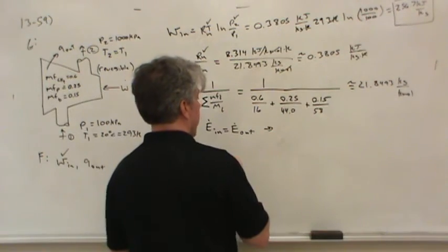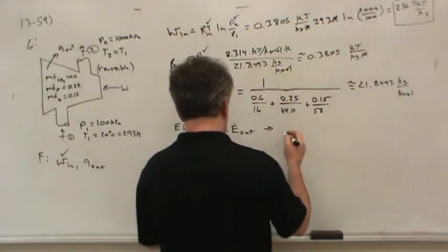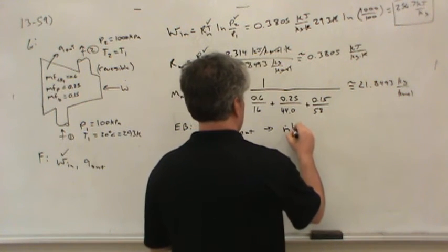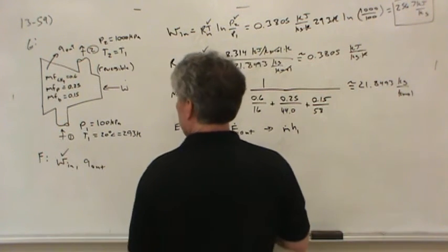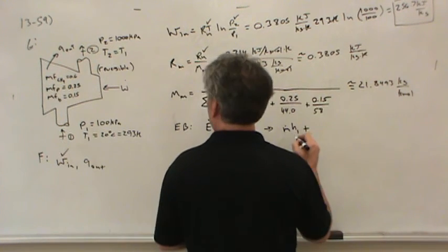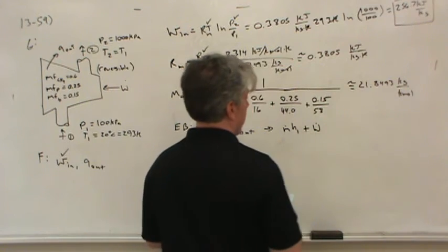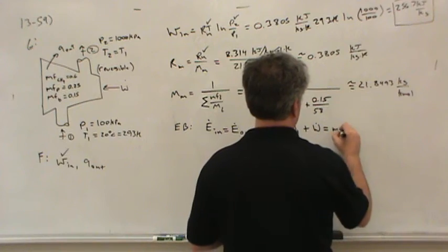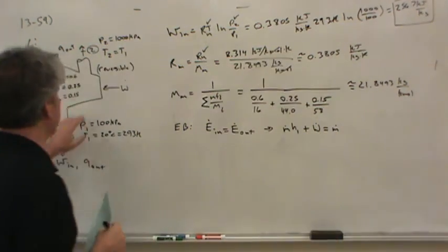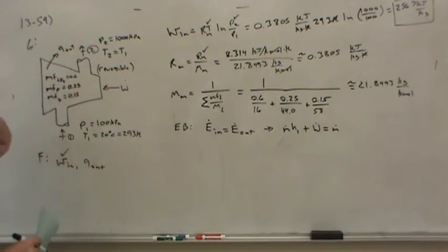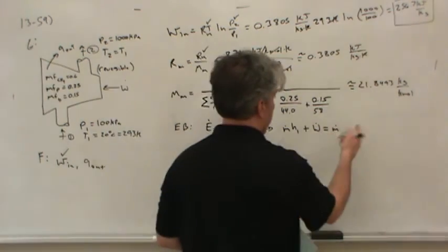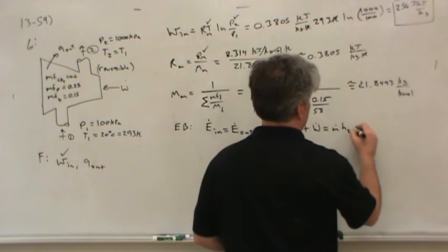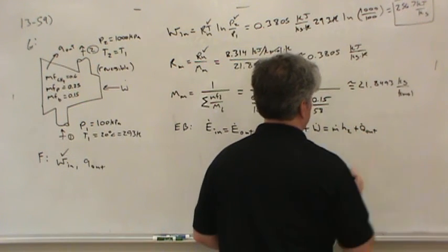So on the left-hand side of the equation, we'll have the mass flow rate times the enthalpy in state 1 coming in, plus the power input in the form of work equals, what do we have leaving? Mass flow rate. The mass flow rate at 1 and 2 is the same. It's single inlet, single exit, so I don't have to write a subscript 1 and 2 here. But anyway, enthalpy in state 2, that's what the exiting stream carries with it, plus Q dot out.